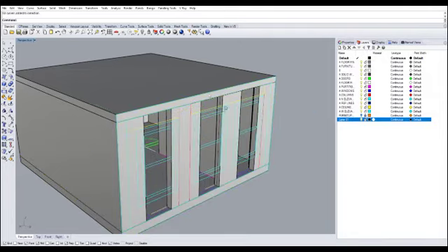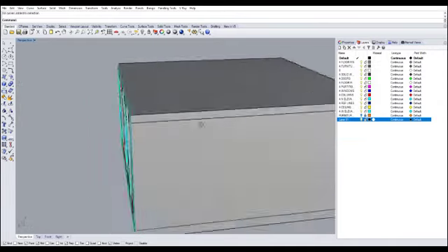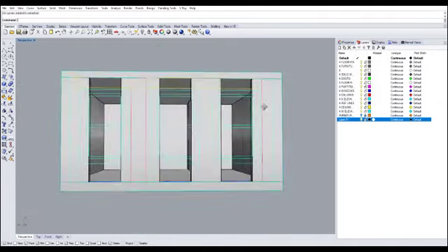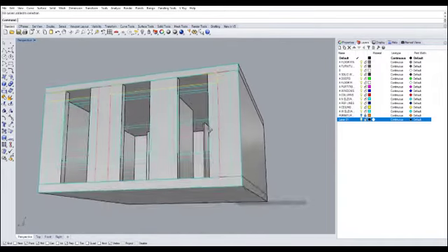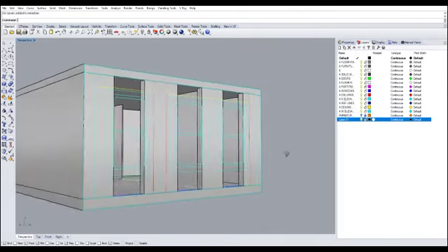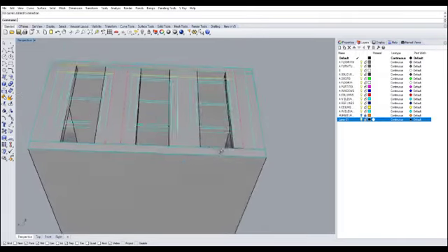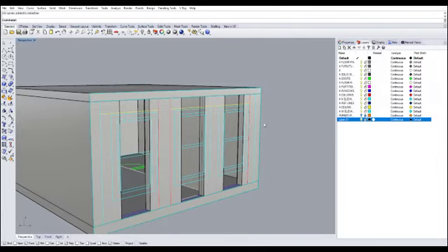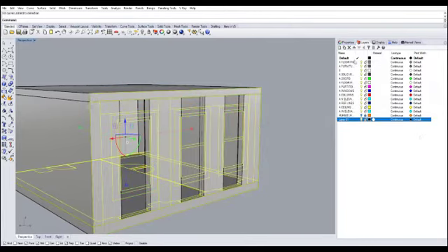Do not click off anywhere. If you did that, the lines are no longer selected. So be very careful when you're doing this exercise. If you are selecting objects before you do something, make sure they're still selected. If you select any other things on screen by accident, you'll unselect your stuff. So once again, right-click only on the layer that you want to move your drawings to. I'm going to say change object layer. That's how you bring the stuff that you selected into the new layer.